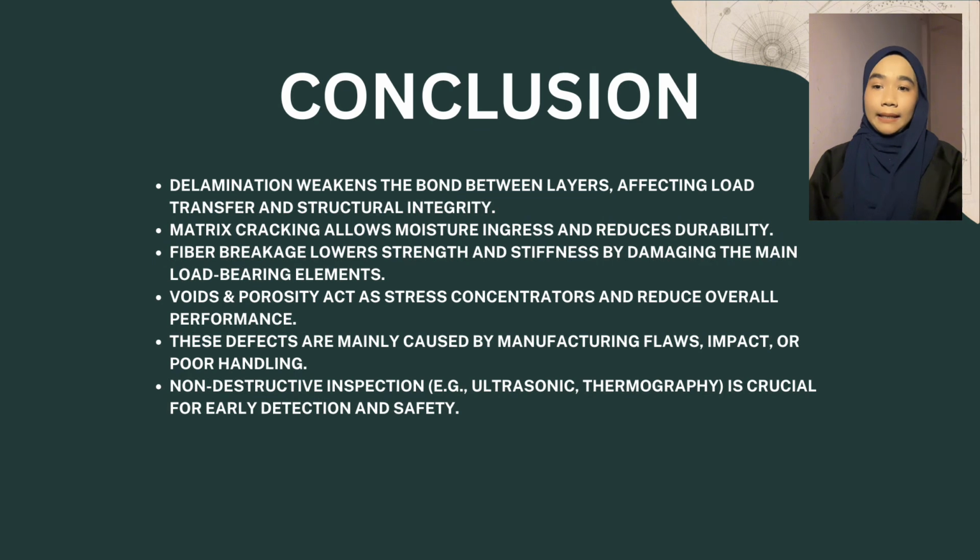Voids and porosity act as stress concentrators and reduce overall performance. These defects are mainly caused by manufacturing flaws, impact or poor handling. Non-destructive inspection such as ultrasonic and thermography is crucial for early detection and safety.